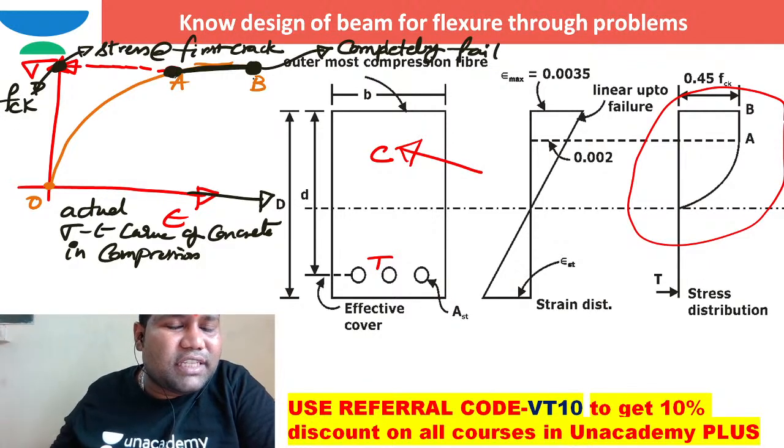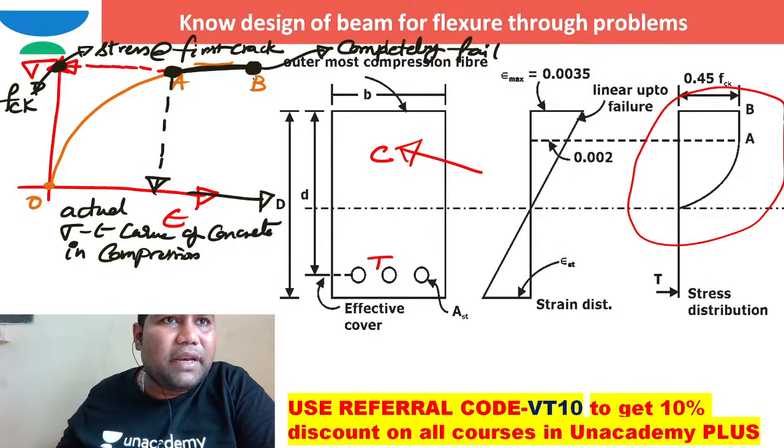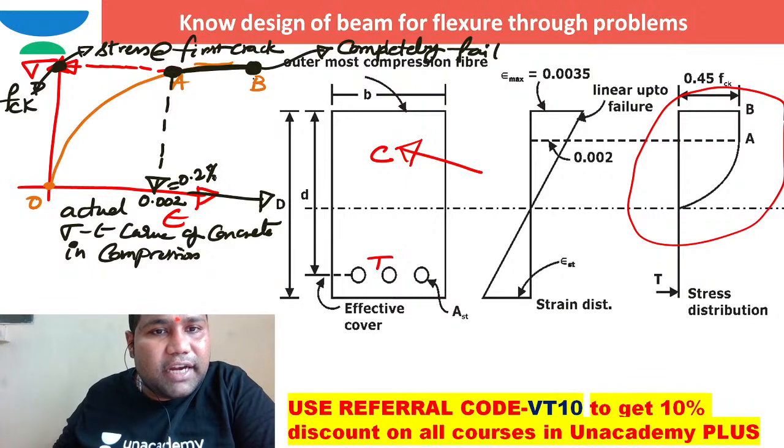But the strain at which the first crack is happening is always constant. What is the strain at which the first crack is happening in case of concrete in axial compression? It is 0.002, which we call 0.2 percentage of strain.